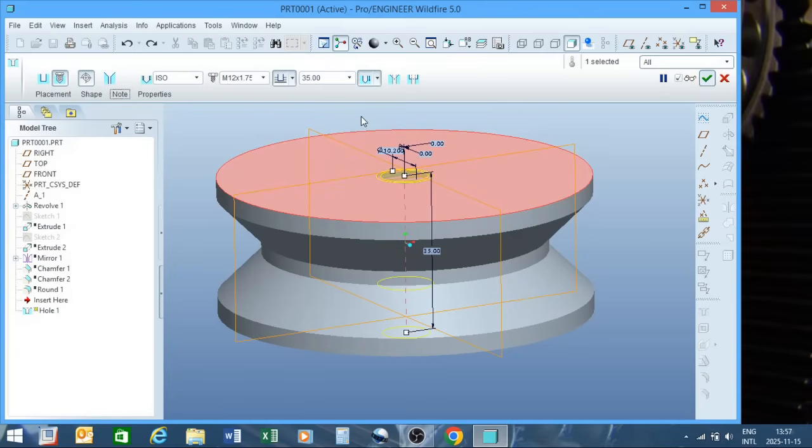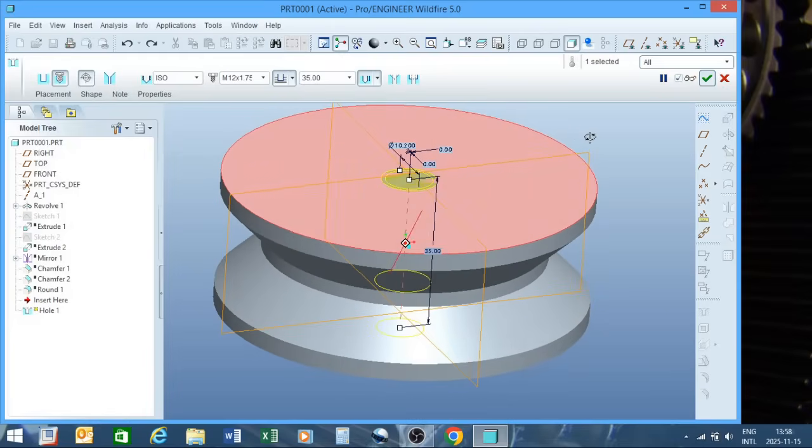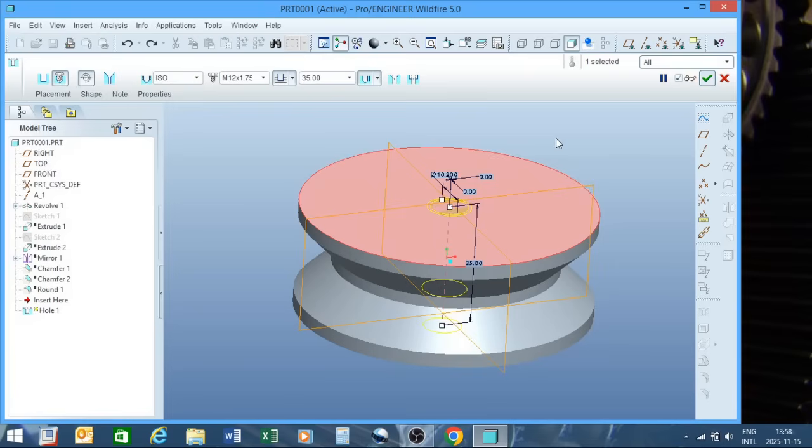Which it will give you when you go to your detailing. It will be there automatically, which is a very nice feature, so you don't have to type it all in when you do your detailing manually. It actually makes your life a lot easier. So this is a very nice feature for threading if you want drilled tapped holes in your parts. That's actually the best one to use.